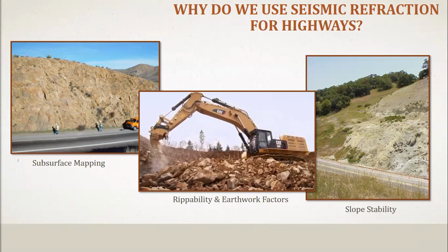A vast majority of our seismic refraction projects involve slope design, stability, and repair. With seismic refraction and other methods, such as electrical resistivity imaging, we can determine the depth and extent of landslides and debris flows for remediation and mitigation. We can also determine geotechnical characteristics such as dip and structure, as well as velocity of the subsurface units, which provides data to the design team so they can use the appropriate layback and angle for cut slopes. Overall, seismic refraction can provide useful information for design and construction.